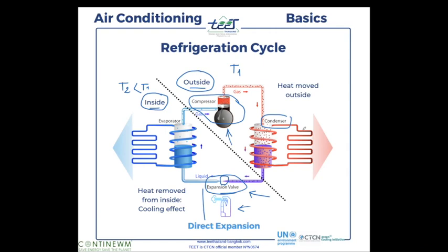That's really what we call the heat pump. Because on this side, on the coil, we absorb the heat because we just release the pressure in the gas, okay? And here, we remove the heat from the compressed gas with high pressure, okay? And so on and so forth. After the compressor and the condenser, the gas is cool at the good temperature and at the good pressure, and we release the pressure again. That makes what we just checked with this experience.